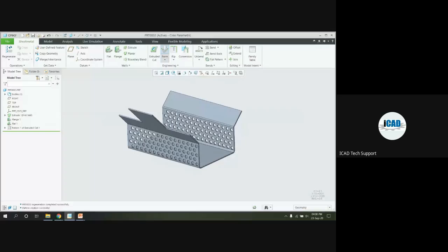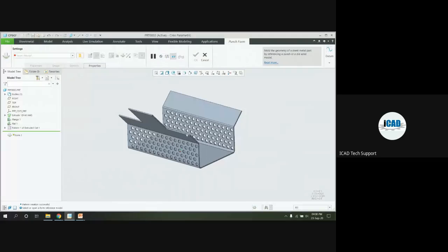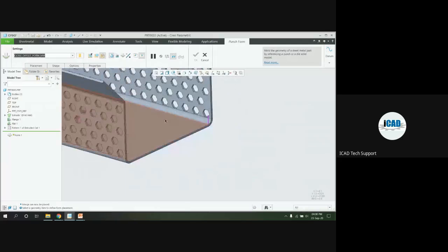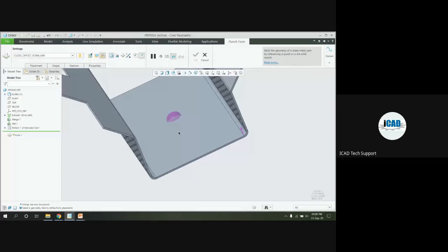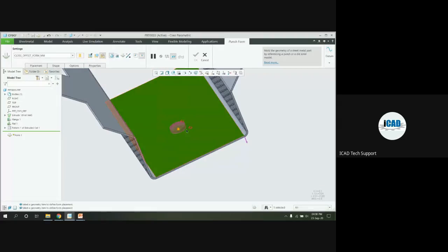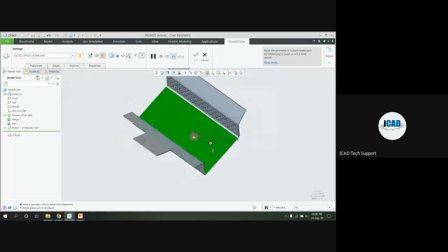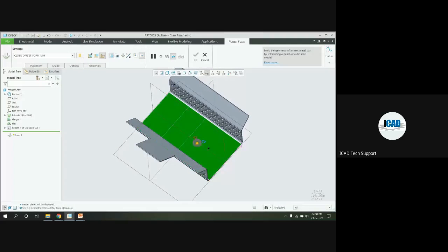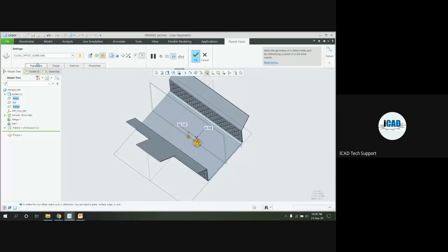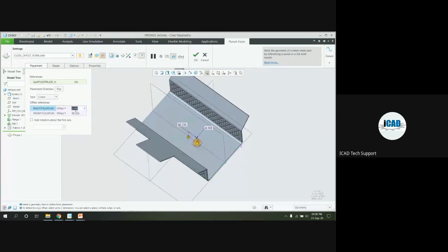If you want to add forming operations, the forming tools are available. You can directly import these shapes, place them on the top side and give the references again, like when we are creating standard holes. This way we can give the placement at a center.